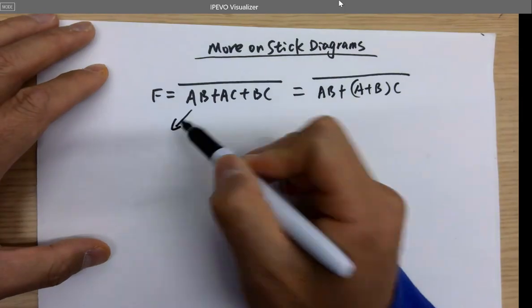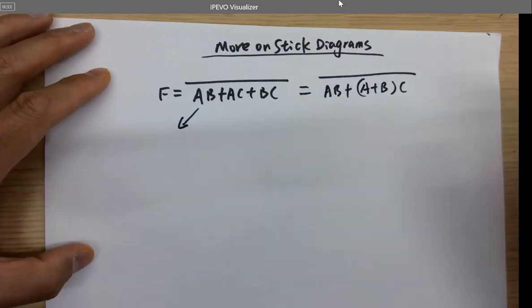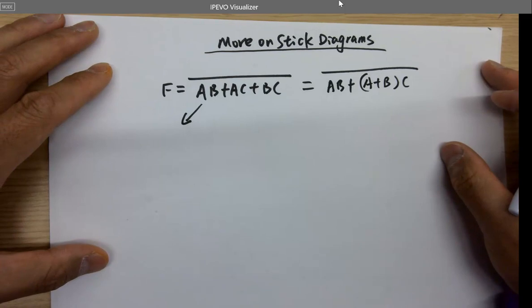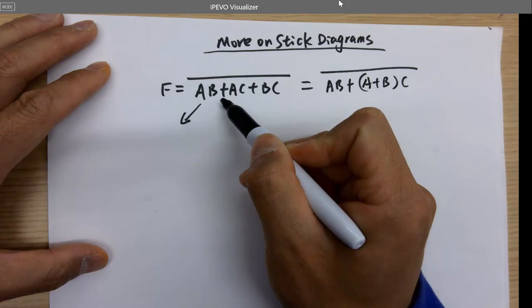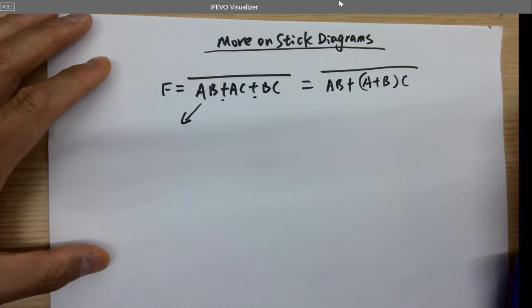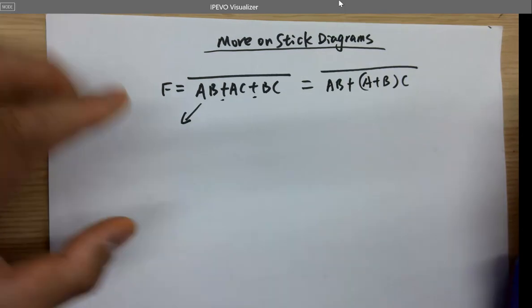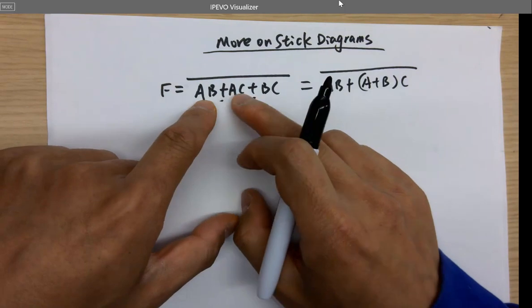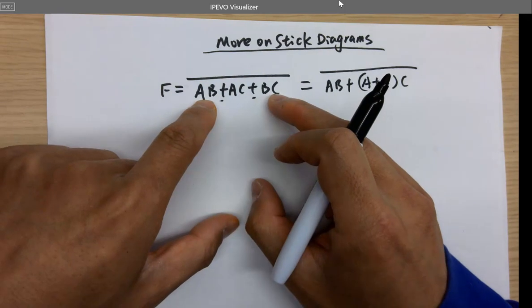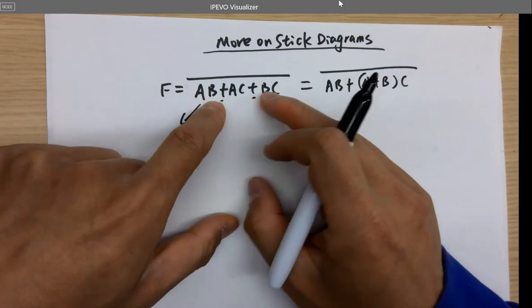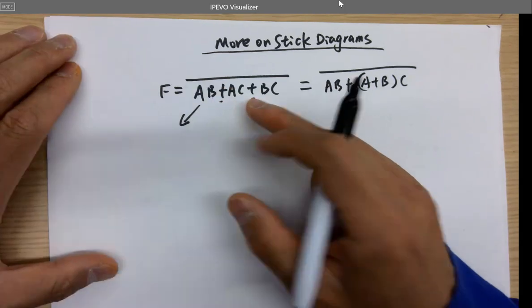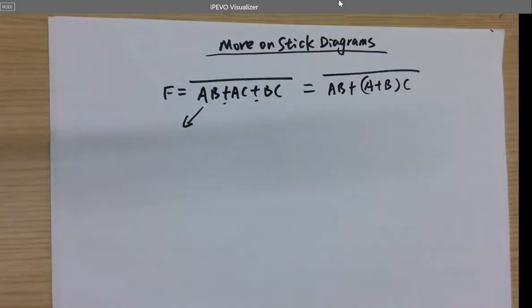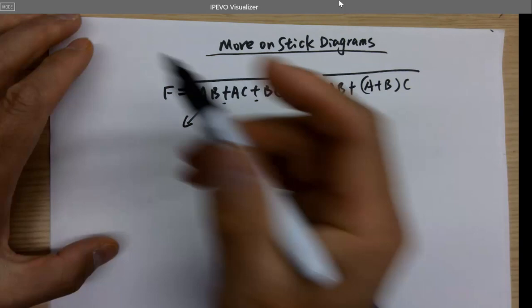So if we directly draw the schematic from here, these are AND logic, and in between them are ORs. So expecting, you know, 1 block, 2 blocks, 3 blocks. On the top for the PMOS, they should be in series because that's the OR logic. You have to think about the NOR gate, right? NOR gate.